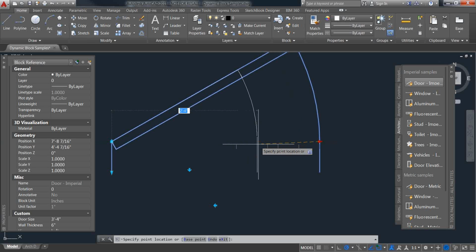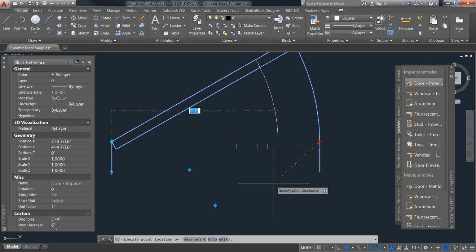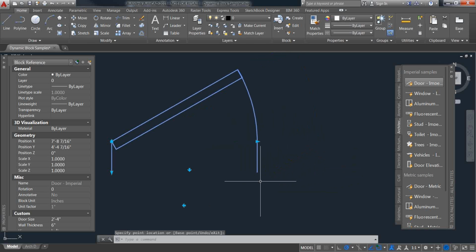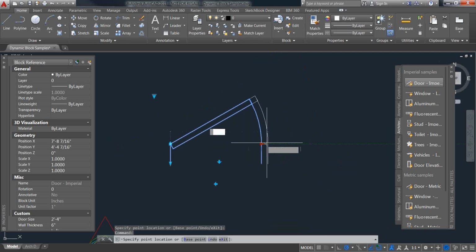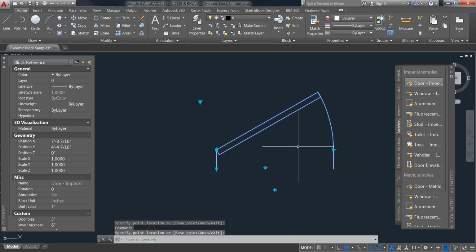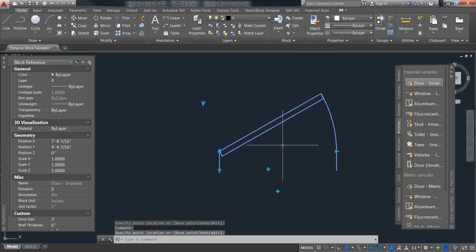So if you have a standard catalog of part sizes, you can increment that. You can build that in either as a set increment, like 1, 2, 3, 4, 5, or we can build a table. In this case, you see we have 2 foot 2, 2 foot 4, all the way up to 3 foot 4, but it skips. See, there's a couple of gaps in the little hash marks. Those are standard door sizes. That way I don't accidentally create a custom door size, which would have to be custom ordered.